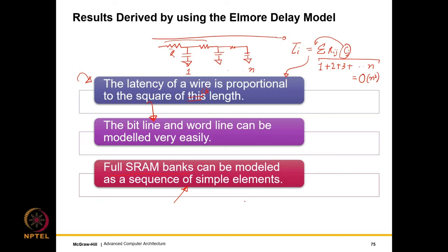So what Cacti does is that whenever we want to, let's say, split an array, we need to compute these 3 quantities, right? So of course then we will split it, and then after a split we can do further splits, right? We are not limited to one split, but we can split it once, and then split it once more, and so on. So as we had seen, we split a bank into a sub bank, a mat, a sub array, and so on. It doesn't matter, it can even be a 10 level hierarchy, but essentially at every level this is what we need to compute.